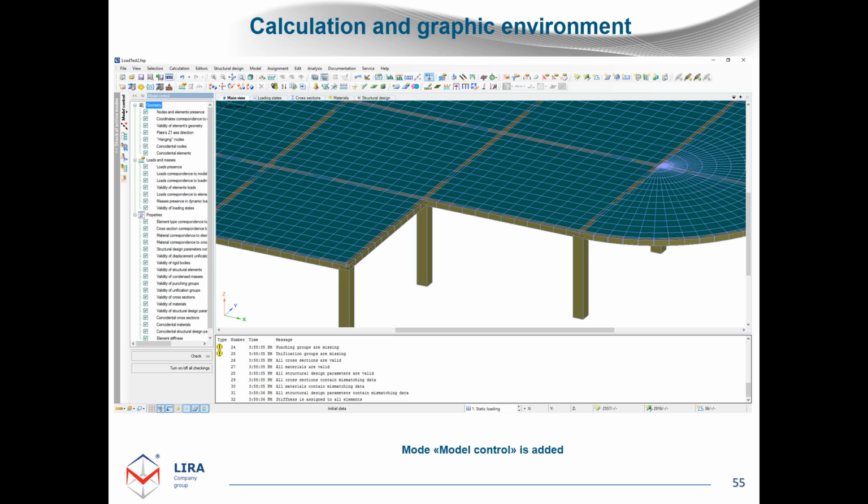In this case, we have a warning about similar cross-sections in the design scheme. This means that absolutely identical cross-sections by their parameters have different names. Probably there was a typo made somewhere when setting a cross-section.